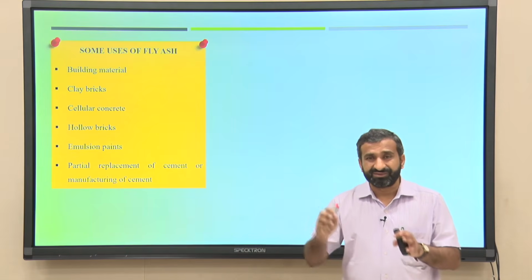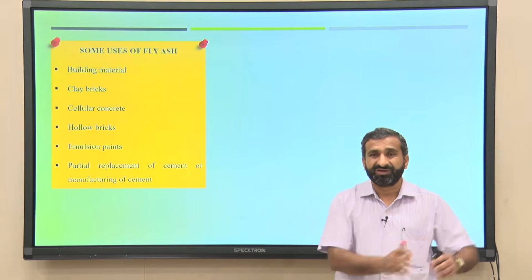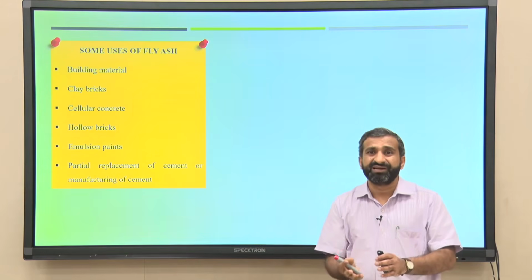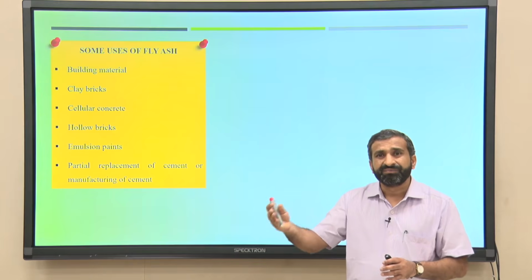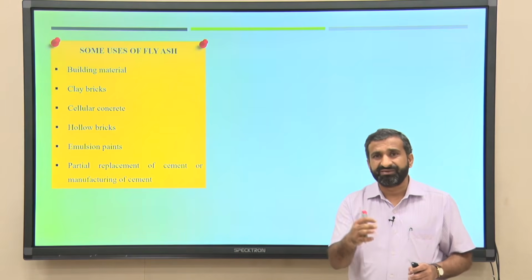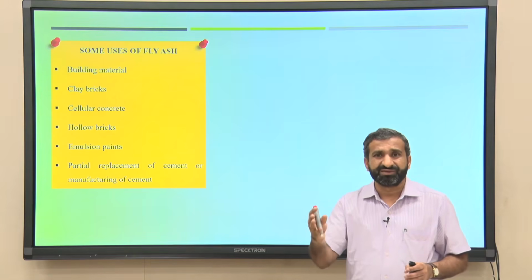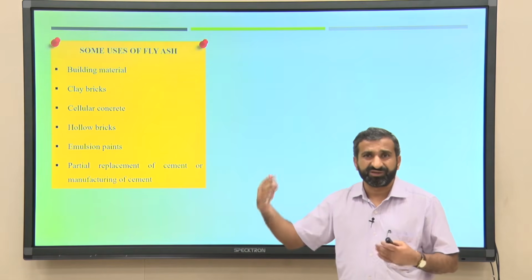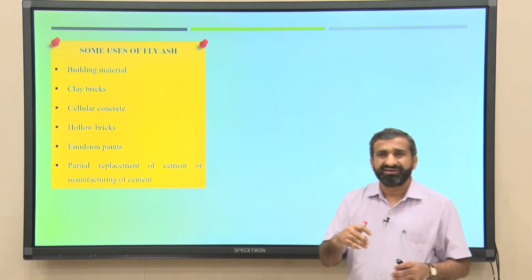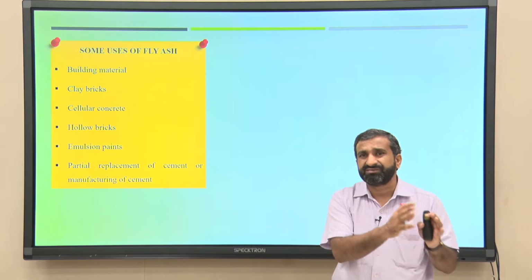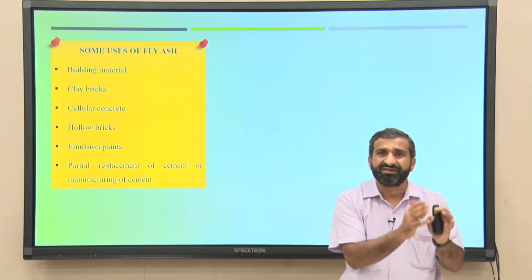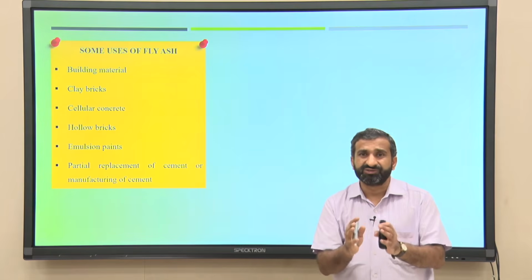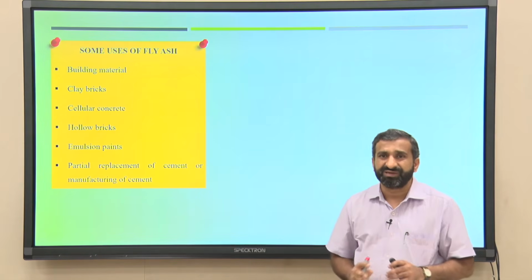So it was always proposed that the fly ash produced in coal power stations could be added to prepare the fired brick. If you add maybe 5%, 10%, the compressive strength should be more than the available standards. And these kinds of ashes are beneficial because they also contain calcium and silica, which are also required to increase the strength of the material.